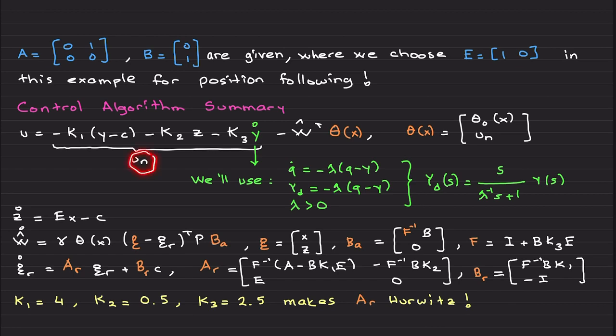So to summarize, with model reference adaptive control with PID nominal control, you have this UN nominal control signal, and you have theta of x. Theta of x includes not only the original structured basis function, but also nominal control because of the lambda. Y dot encoding, or in general, in industry, Y can contain measurement noise. So practically speaking, we would like to use a filtered Y dot.